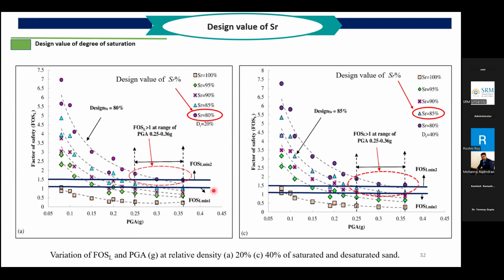This is the boundary under equilibrium condition where the factor of safety is considered 1. Normally any designer may expect a factor of safety of 1.5. So if we take 1.5 as the upper limit, and this boundary for our problem, anything below this is dangerous, where you are expecting liquefaction. Above this is a stable zone.